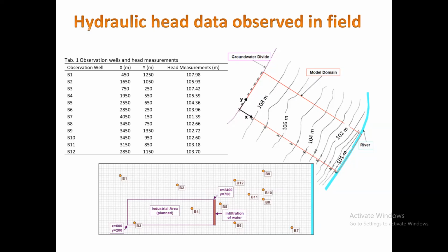So basically, you get the geometry of this table, the property of this material, and your stress and strain equations, you put them there. But then how would you know that what you have in your computer represents this one? You do an experiment on this one, and then you see whether the result of this experiment is similar to what I'm observing in my model. If they are the same, this means that this is a calibrated model, and now you can do anything with it.